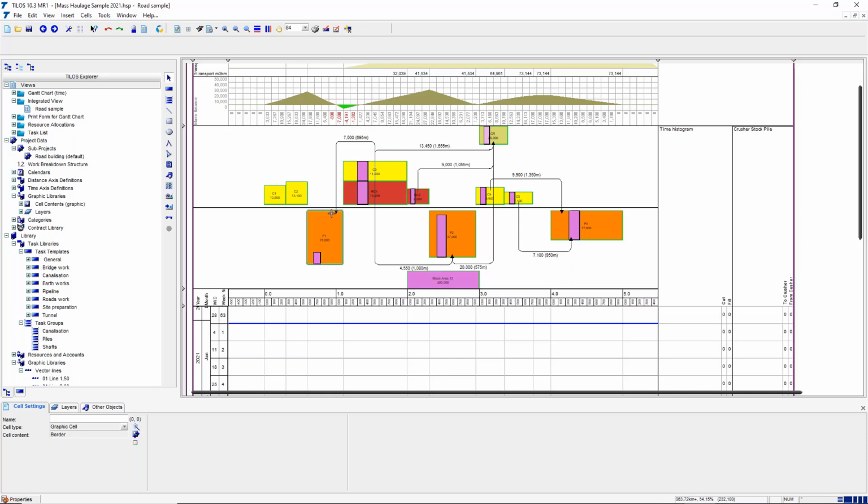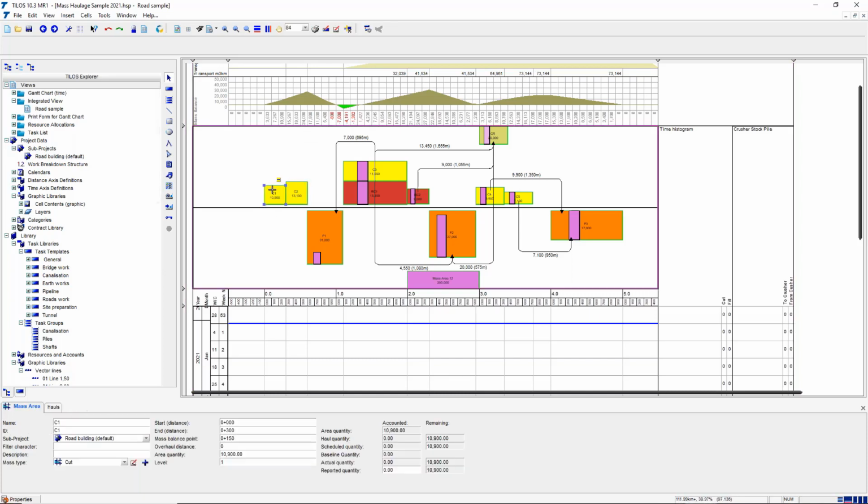And so we can find out where there are hills, and we can indicate what are called mass areas and the quantity of materials available at that space. And we can create those manually in Tilos, or we can import them. So underlying that are what's called mass types. So that is fundamental types: rock, spoil, things that have been cut, filled. So there's a sort of mass type creation, and then in the project data,